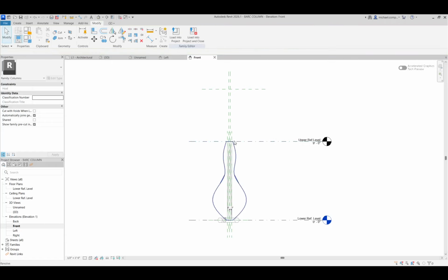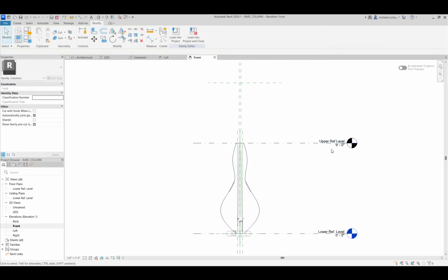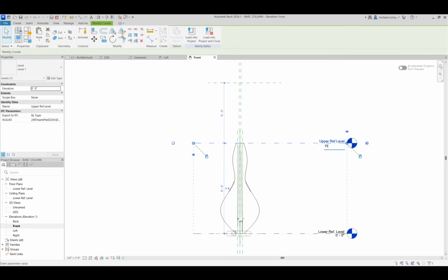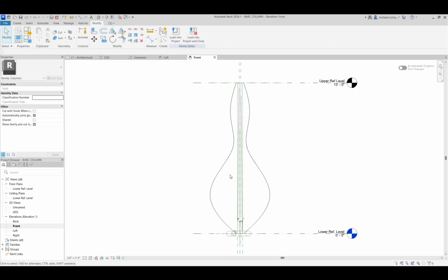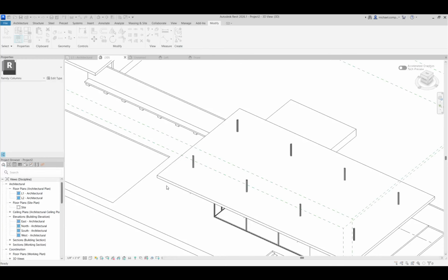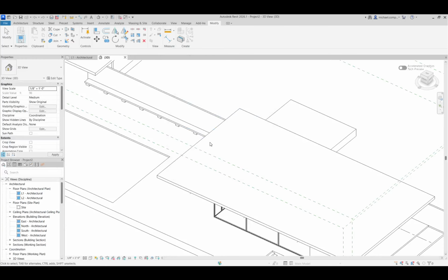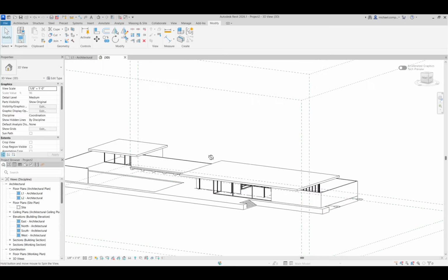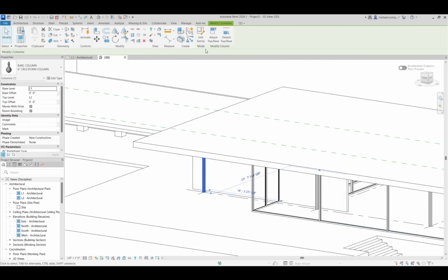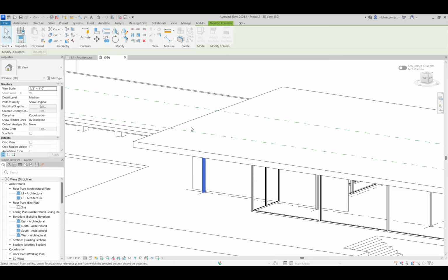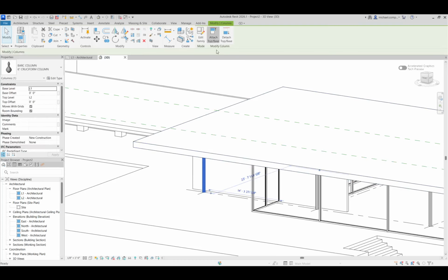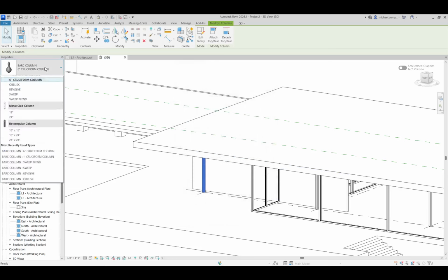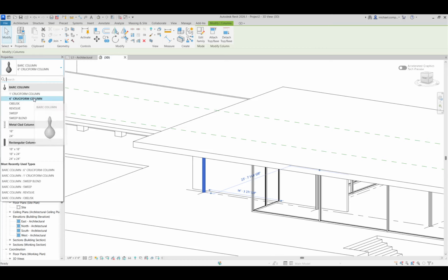There we go. Okay, so now those are all in place, right? And I can change this to 15 feet to make the point, but notice how they all stretched. All right, so I'm going to load that back in and now overwrite. Where'd they go? They all automatically did that. Why did they do that? Because they're attached. If I detach it, and then give it a height of something, it won't flex because it's set at 9 feet.